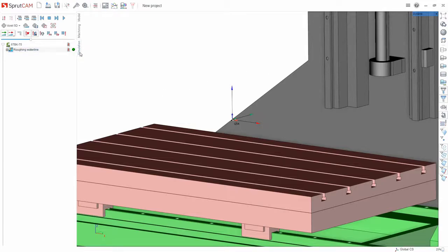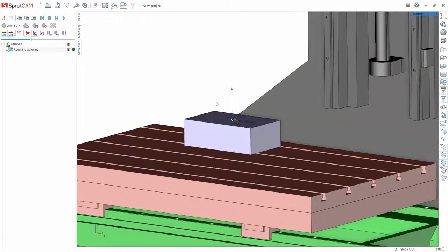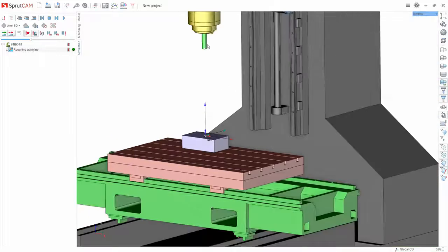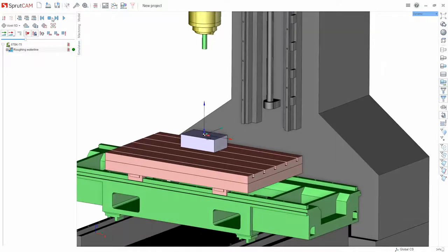To do this, switch to the Simulation tab. Here we include the machining result visibility. Here we see our part. Here is our machine scheme and tool. Let's make the speed of simulation a bit less. And here I'd like to add that there are several simulation modes. They are Solid, Voxel 3D, Voxel 5D, and Rock Solid. Let's look at the example of Voxel 5D. It's fast enough and high quality. Press Simulation.